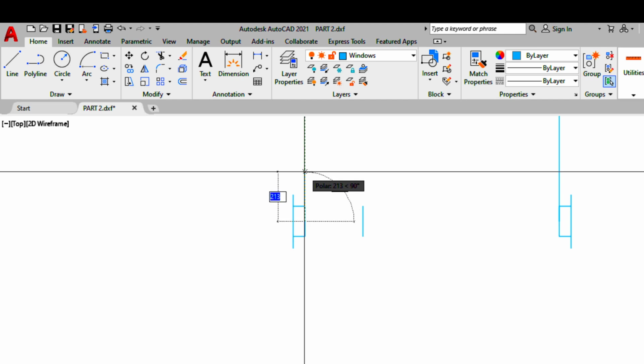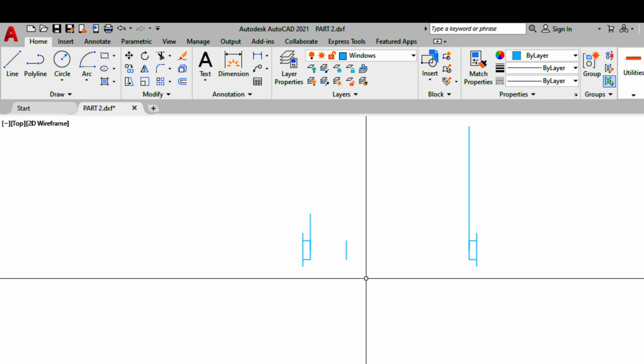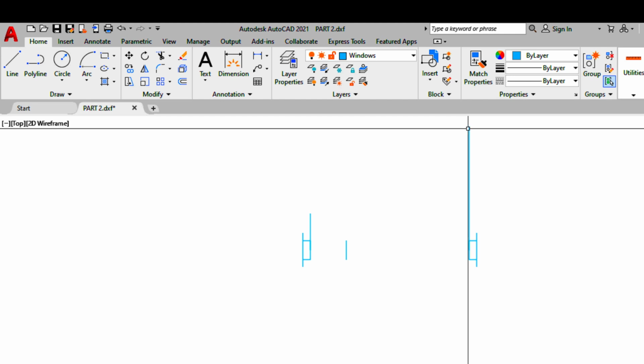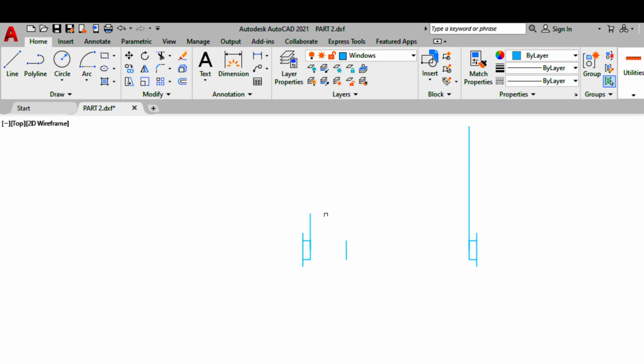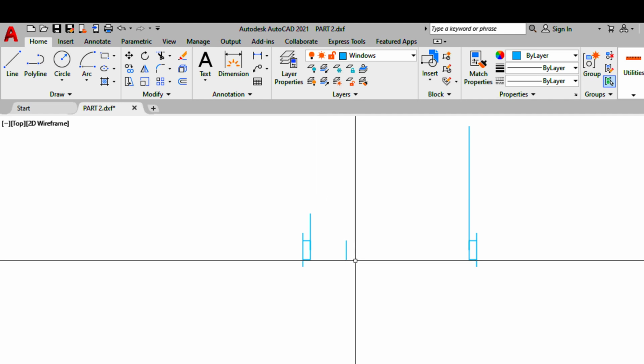Then I type 250mm this time around instead of 300mm because the door frame, which is 2 inches, has occupied part of the 300mm space. Then I press enter on my computer keyboard. Okay, now the next thing I need to do is to create a path for this door as it swings downward, and this other one as well, which is an arc.